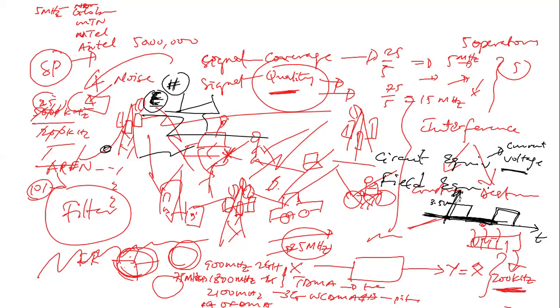So it means that in all of these, we are looking for the analog equivalent of my signal, based on the fact that we now have to modulate my bit sequence with a modulation scheme so as to have a carrier that we can transmit through a physical medium like a coaxial cable. We want that information to be equivalent to some voltage values. And we know that we can now say this is 1, this is 0, this is 1. So in transmitting my 101, it is some 3.5 volt variation with respect to 0. And now we say this is a return to 0 coding scheme. It could be a non-return to 0 whereby my 0 comes down to the negative.